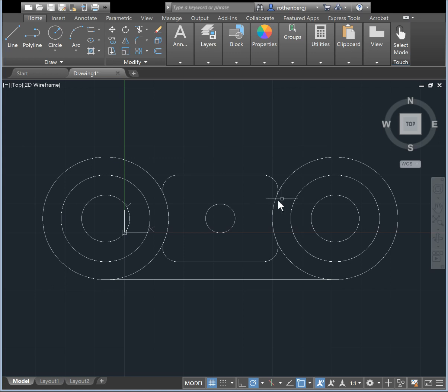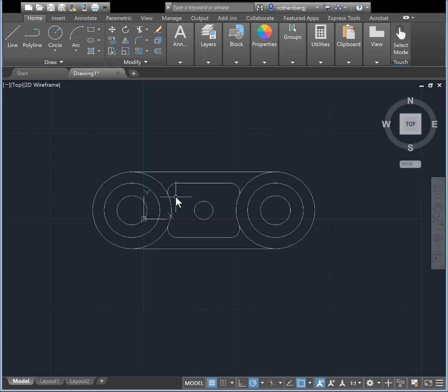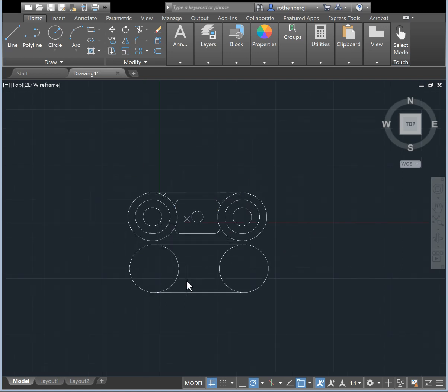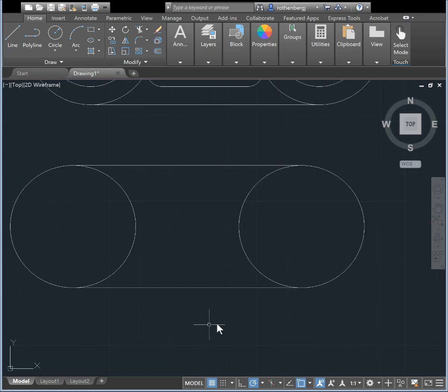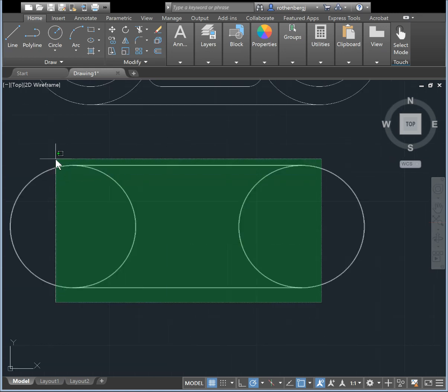So we are going to start by making a few different pieces that we will use the join command on and turn them into polylines, which will be very important later. First, we're going to select the outermost line and the two outer circles, and you're going to somehow copy them. It doesn't matter how. You could use copy base or Control C, but get a copy of them. Don't delete the previous ones. Don't just move them.